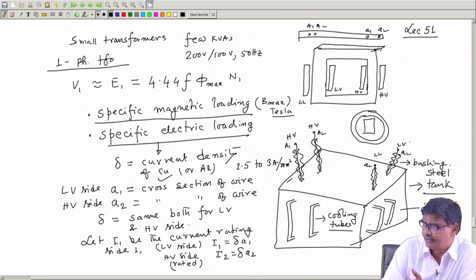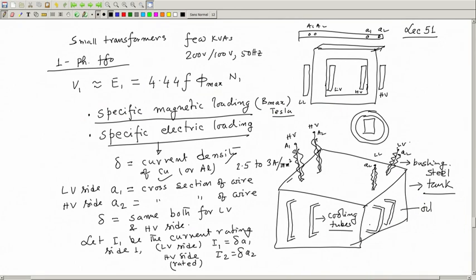This is the tank inside this transformer, and terminals will be brought out through bushings, through the conductors, LV side, HV side. You can easily make out which one is HV if the insulation level is more, that is HV, and this is the LV side. LV side thicker conductors. Okay. Anyway, so it is immersed in oil.